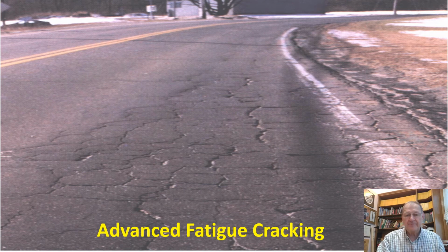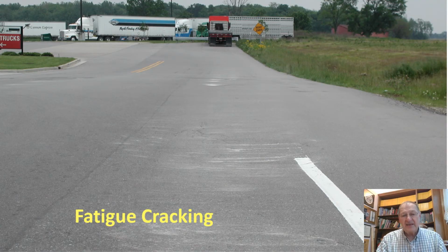Now, I did take this picture. This pavement is a private pavement at a truck stop. And you are looking at a 3-year-old pavement that is 10 inches thick. And it is fatigue cracked all the way through.